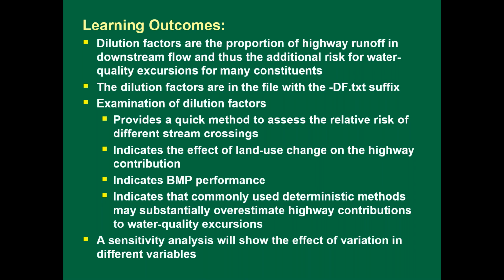Well, with SELDM, you can do a hypothetical analysis where you use your existing site, but you model it as if it's down in the basin. And you can see the additional dilution that will occur from all the stormwater and base flow inflows between the actual highway site and the actual place where you're worried about a given species of interest.